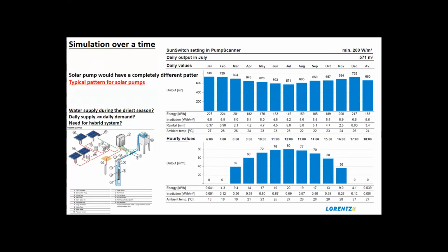On the other hand, you also have to check the situation on the worst solarization, the worst case in the wintertime, when you have little sun, because here you have to check if the pump is going to deliver enough water for the population, if the demand is going to be covered for this population. That's why it's good to have 2 types of pattern, summer situation and winter situation.